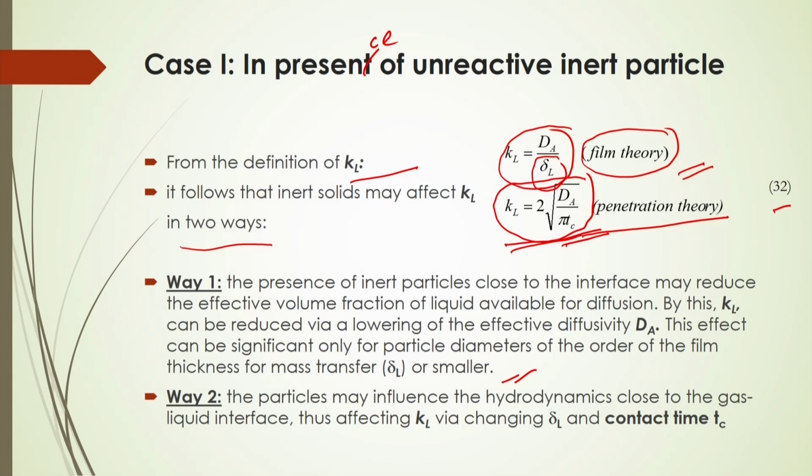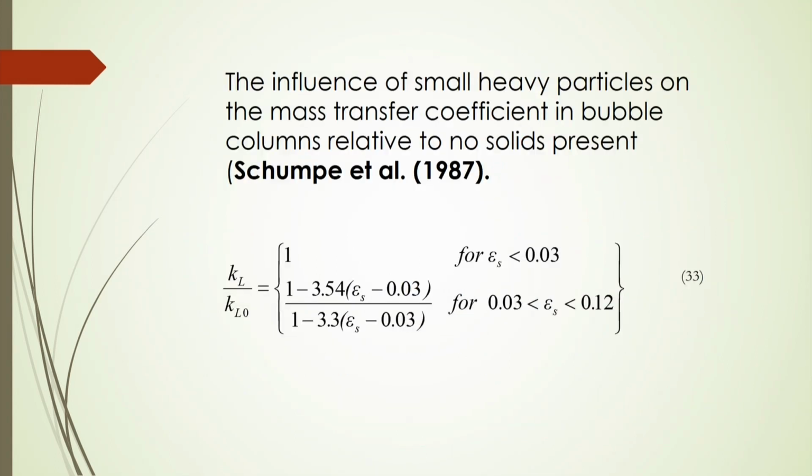Another thing we have to discuss is that the particles may influence the hydrodynamics close to the gas-liquid interface, thus affecting KL by changing the film thickness and the contact time in the penetration theory. The influence of small heavy particles on the mass transfer coefficient in bubble columns, relative to no solid present here, Schumpe et al.